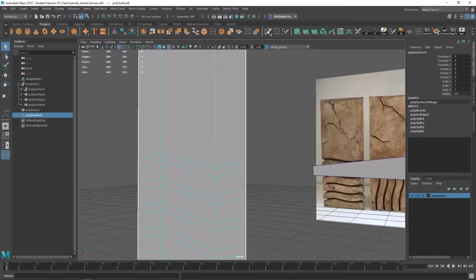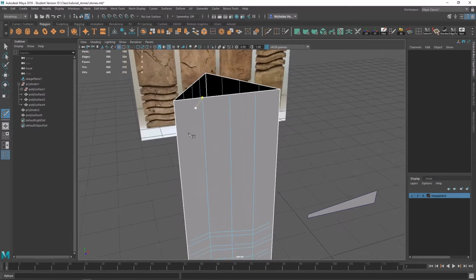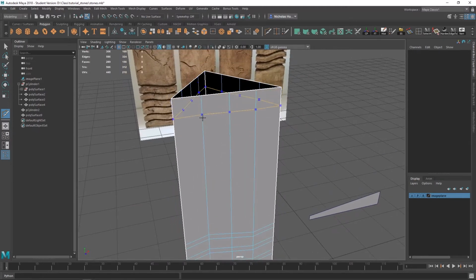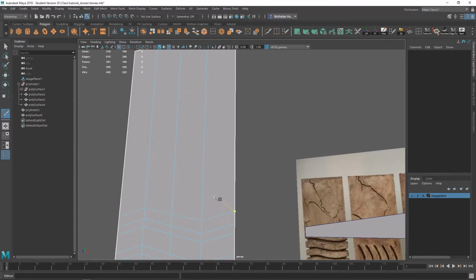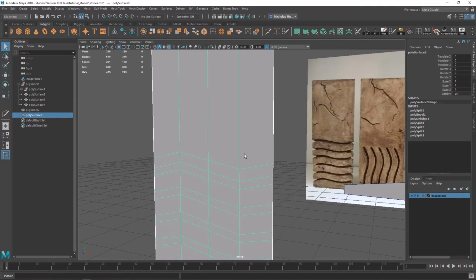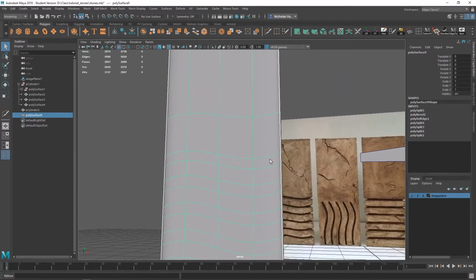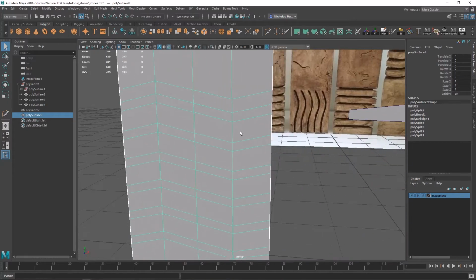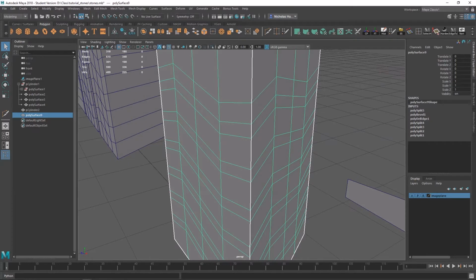So I'm going to add one above it with the multi-cut tool. Hold down Control. It looks kind of wonky because it's going to follow this topology, remember, because it's wavy here. And if you pull this all the way up, it kind of straightens out. So it's a gradual curve. But we're just going to pop one right there. Doesn't have to be exact, just something arbitrary. Now when you press 3, that one's the one that pops up instead of the actual cut in we're going to do. So to do that cut in, it's going to be an extrude, and we're going to extrude inwards.